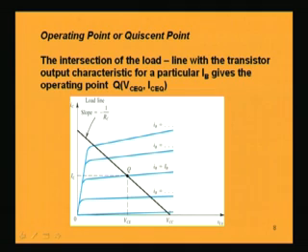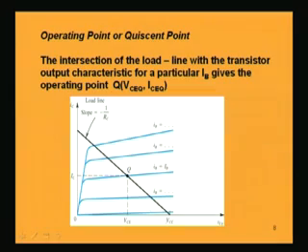So, what is the importance of properly setting the operating point, or by what factor will we ascertain that the operating point is proper? If we look into this output characteristic and this load line, here is the operating point, almost in the middle of the load line.